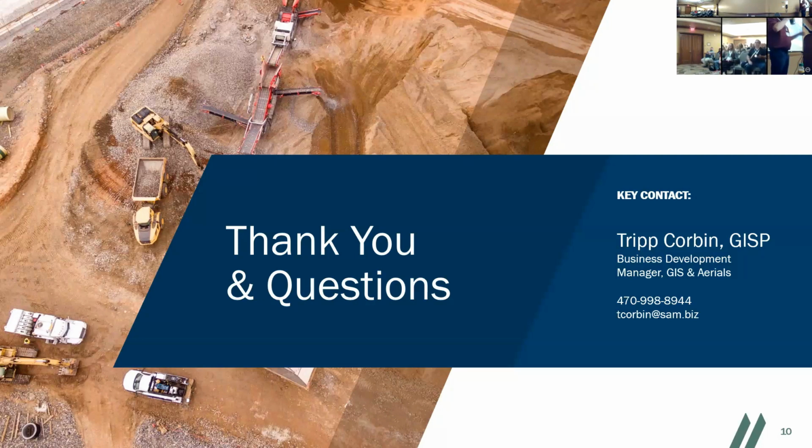Thank you, Tripp. I was going to say, it's not really a question, but to kind of streamline the process, I've been using files from MicroStation and ORD. In the contents pane, before you bring in your drawing, you can open the properties of the DGN file or DWG file and project from the properties layer. It's a section that validates the projection, and then you'll change the projection before you even bring it in. So you're not getting where it brings it into Mississippi and then you have to readjust. You just do that straight from the contents pane.